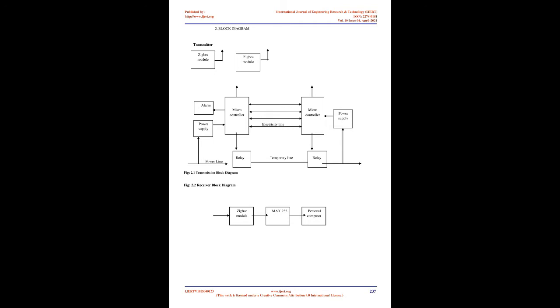3.4 Zigbee. Zigbee is a specification for a suite of high-level communication protocols using small, low-power digital radios based on an IEEE 802 standard for personal area networks. Zigbee devices are often used in mesh network form to transmit data over longer distances, passing data through intermediate devices to reach more distant ones. This allows Zigbee networks to be formed ad hoc, with no centralized control or high-power transmitter/receiver able to reach all of the devices. Any Zigbee device can be tasked with running the network.